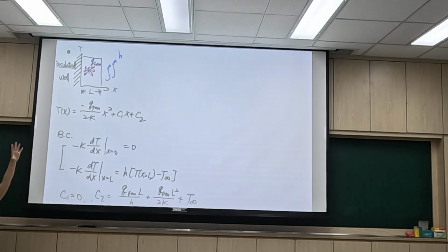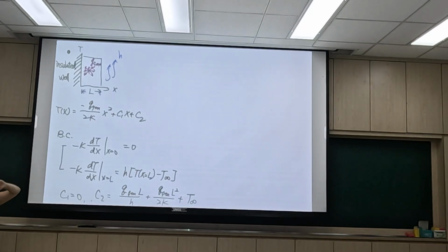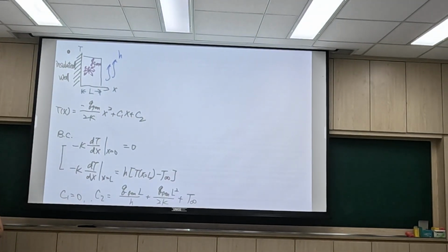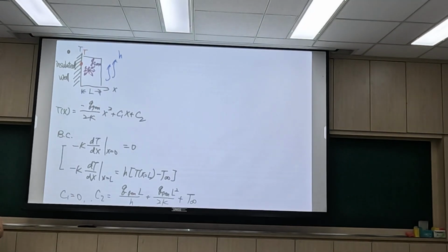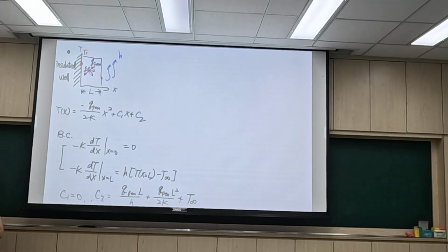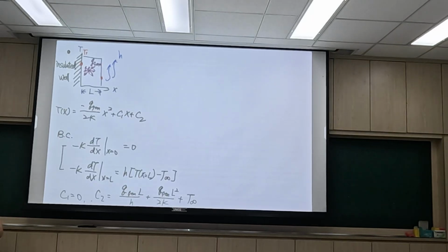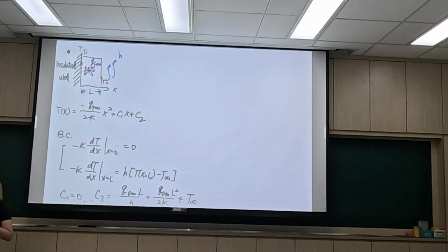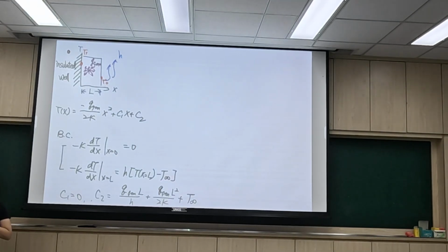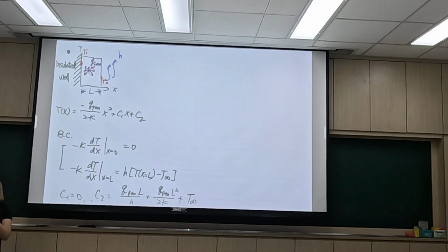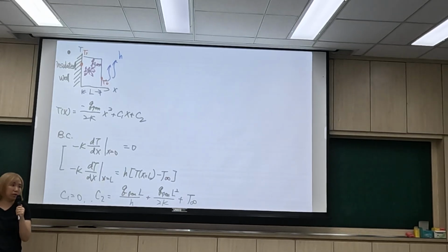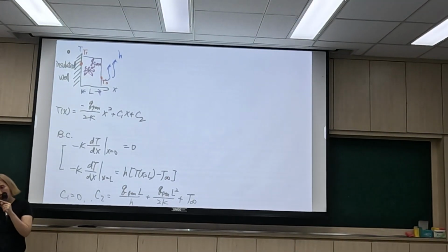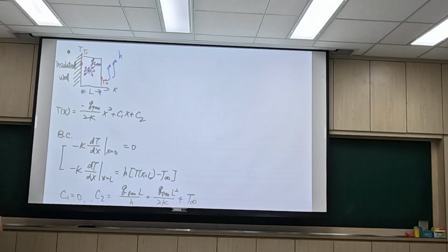If you have heat generation and an insulated wall on one side, the surface temperatures on the two sides, T in and T out, are different. It's not necessarily a symmetric parabola, sometimes asymmetric because the heat won't distribute in both directions. If you want to know the parabolic profile inside the object, you use this equation.